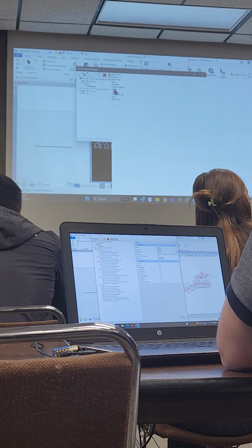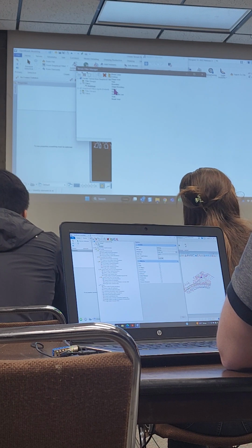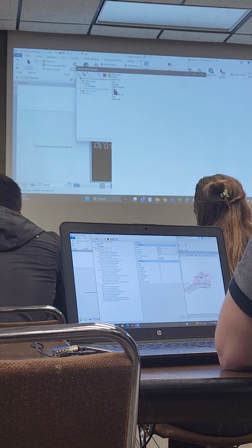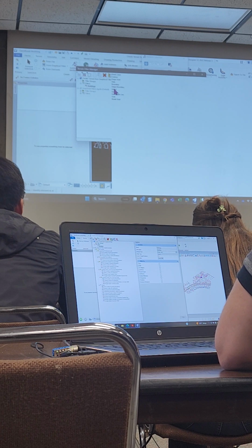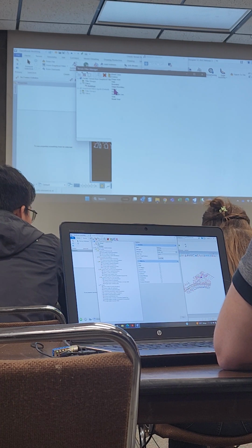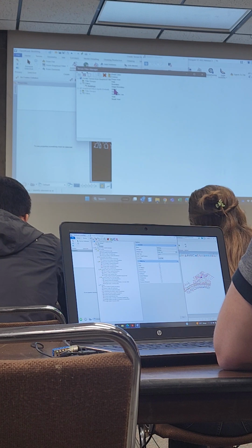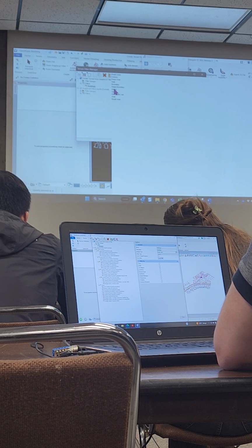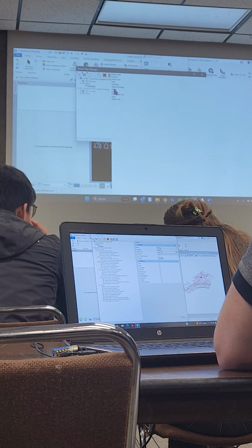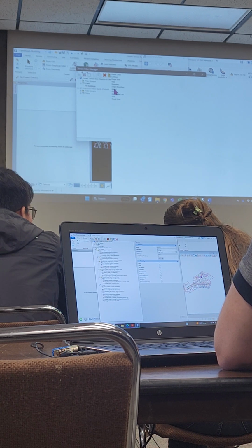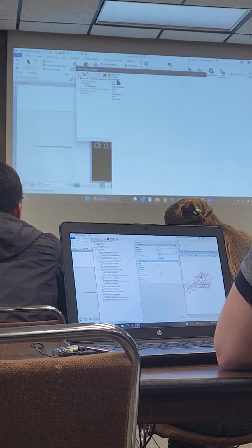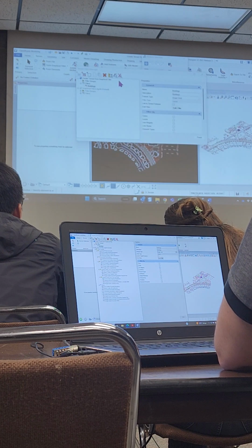So if you have some breaks in your boundaries, like your cut and fill lines, and they don't actually go all the way across, what you can do is create a MicroStation shape inside to fill in all those gaps. Then you can use that boundary as your drape boundary to add to your terrain, and that's going to constrain all of your edge triangles to keep everything inside without having to have a profiled line all the way across. But we're going to set this to drape void.